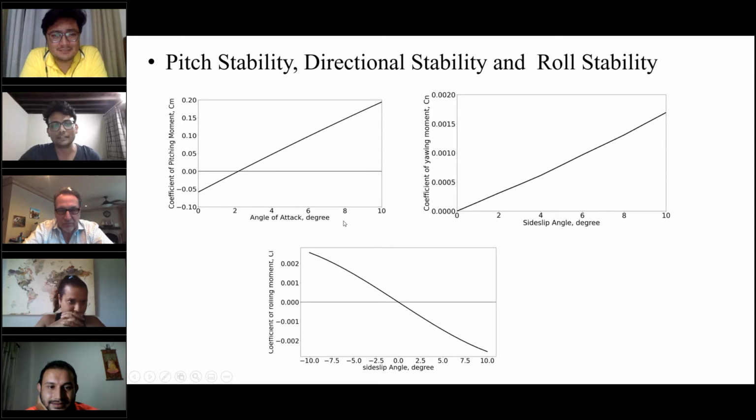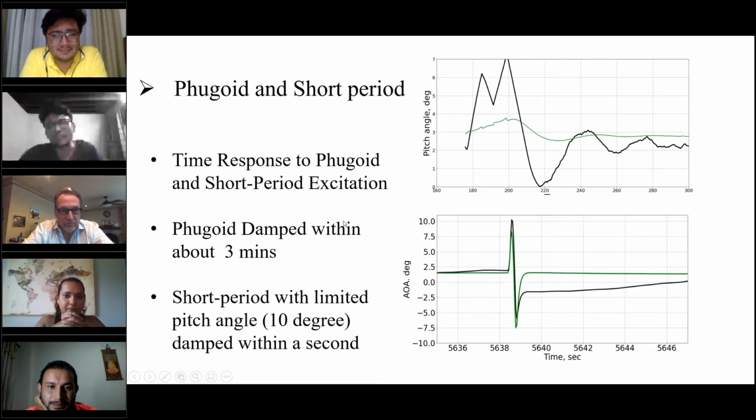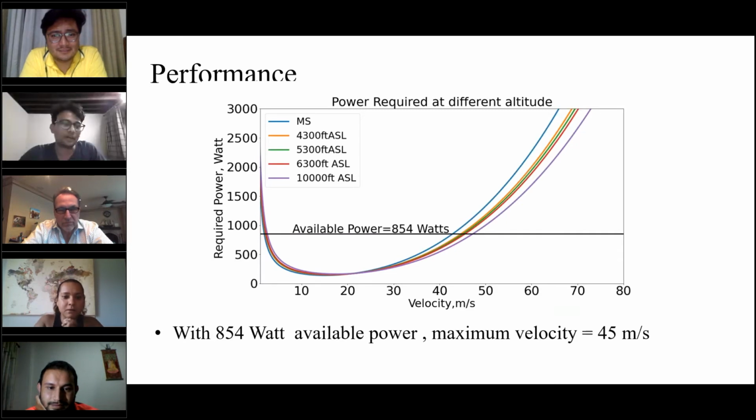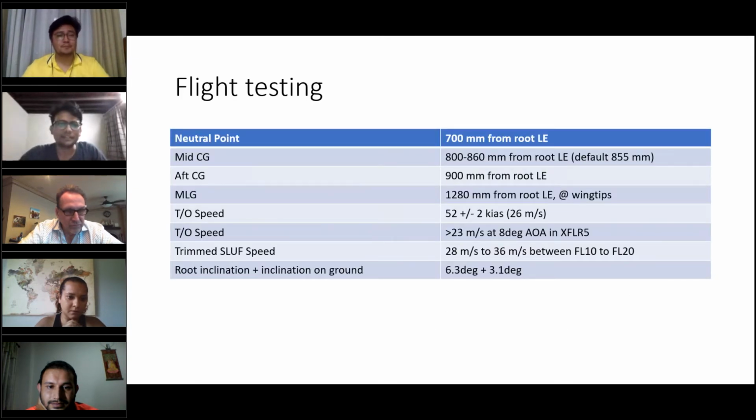When I move to flight test, I want to mention we moved the center of gravity to match whatever takeoff performance we wanted and eventually the flight performance. The center of gravity from VSP was a volumetric center of gravity, and now it has been moved aft quite a lot. That makes the aircraft, in a theoretical sense, unstable. If you look at the details here, we have a neutral point at about 700 millimeters. Here, luckily, we just have the SI units.